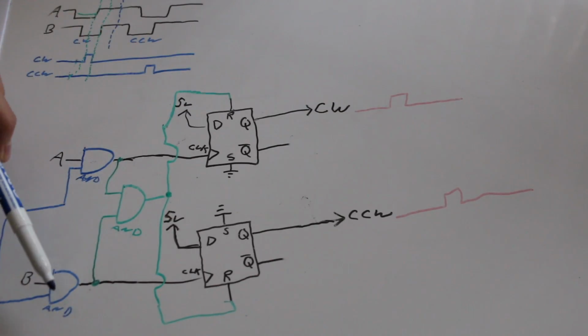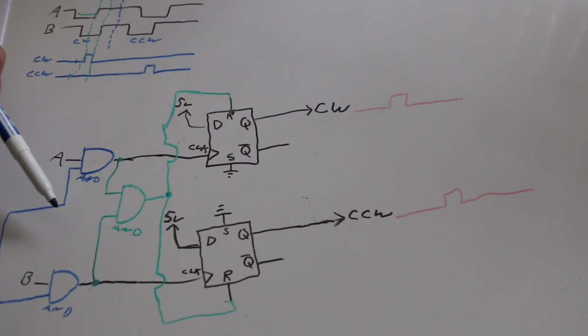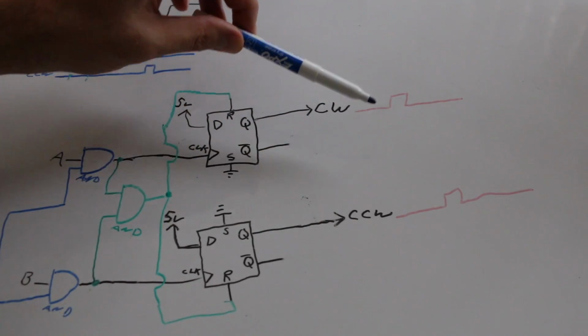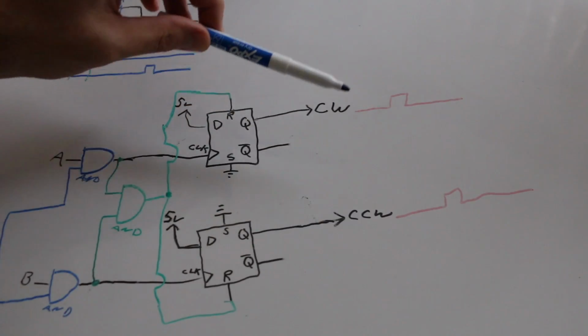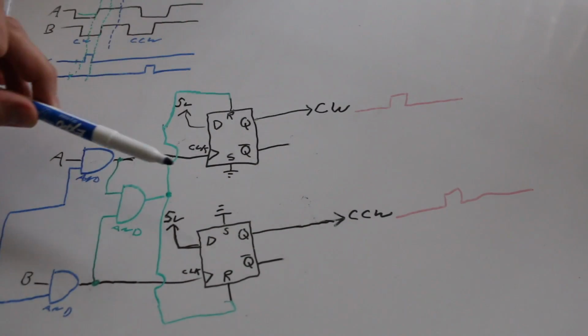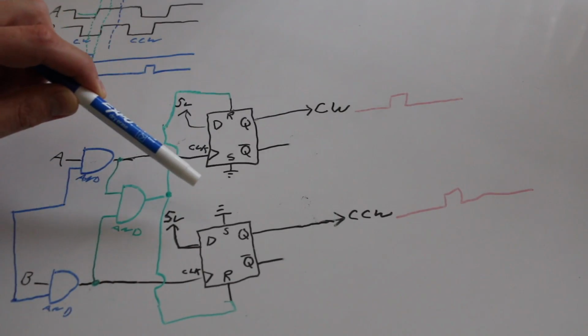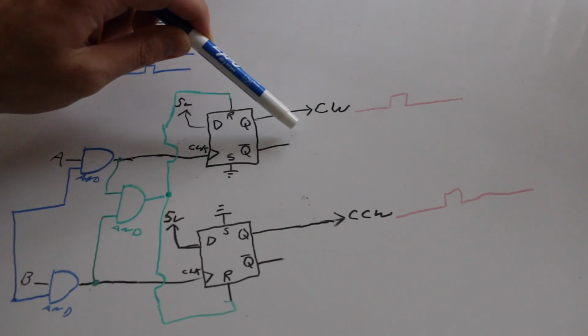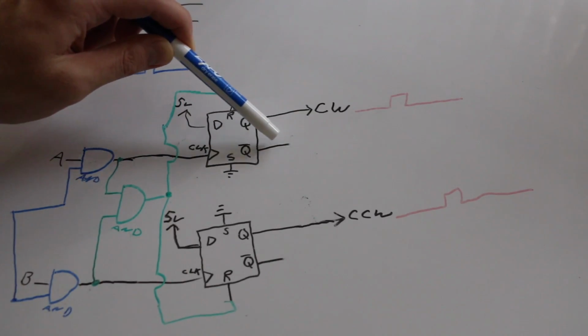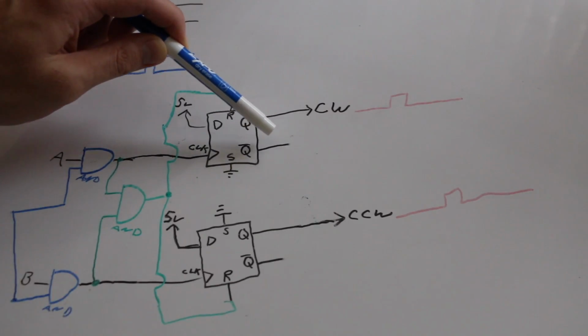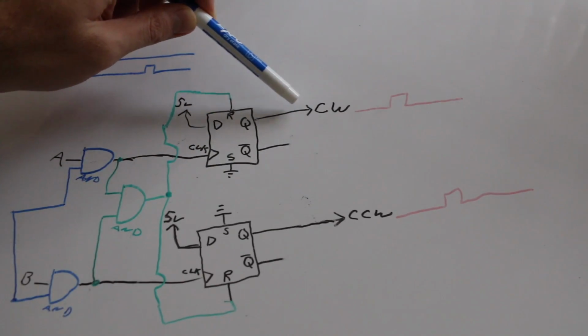We can gate both of these at the same time with the same gate, because as long as we've triggered something, we just want to lock everything out really. We don't care until the cycle's done and we reset. So if we gate these with the same signal, what can we look at here in the process to tell us something has happened and it's time to lock everything else out, bring this gate low? When something has happened, it's the flip-flop outputs that change. Since we have an unused Q bar on each one, we might as well just tap into that and then leave this as a clean signal.